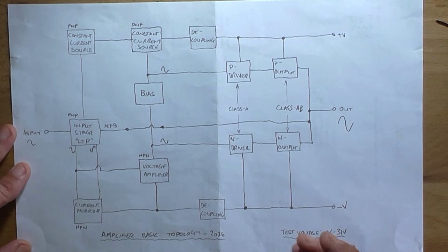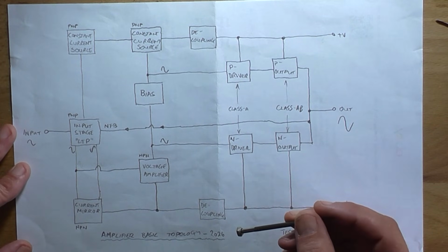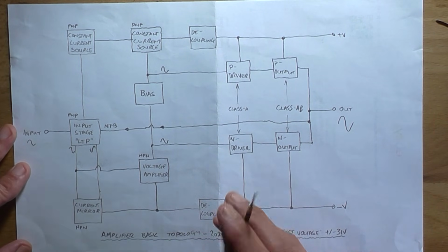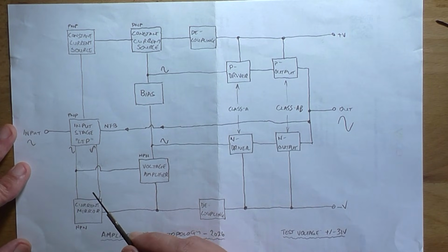Now I'm going to be using a simulation program called Texas Instruments Tina, and we can actually draw the entire amplifier schematic out in Tina and run a simulation on it of DC tests and AC tests to see if our concept is going to work before breadboarding it out, which I'll go through shortly. But first, what I want to do is test the input stage here.